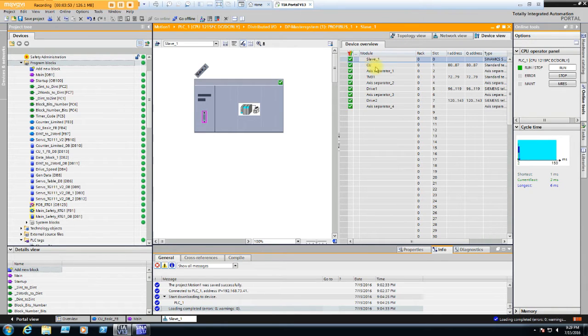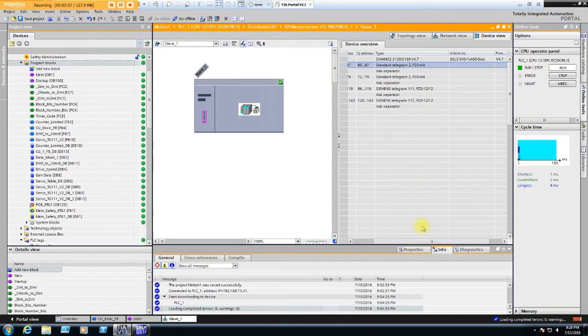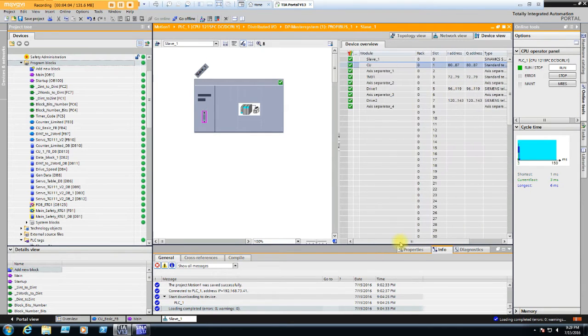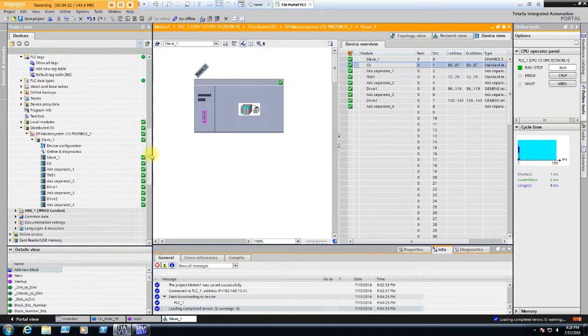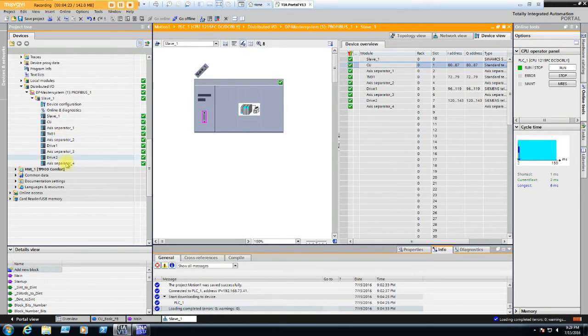The slave is not the CU, but what you get by default is this sort of descriptor, and it doesn't really tell you what that telegram is talking to. So I put my common names that I would call the devices: the CU, the TM31, drive 1, drive 2. I changed those names from the telegram type to something that means something to me, so it actually shows up right here.